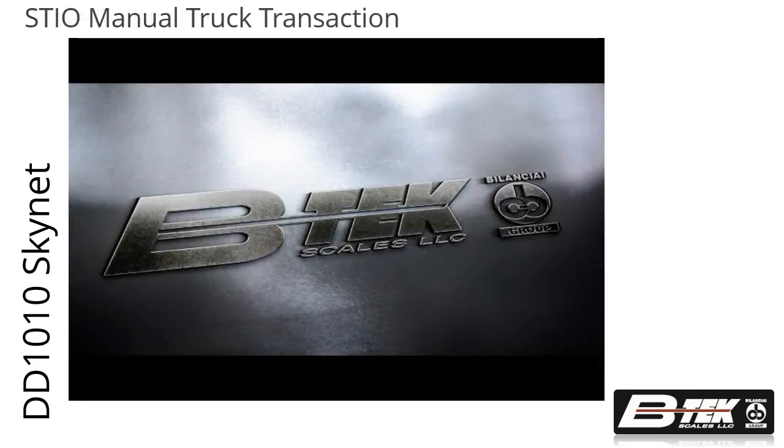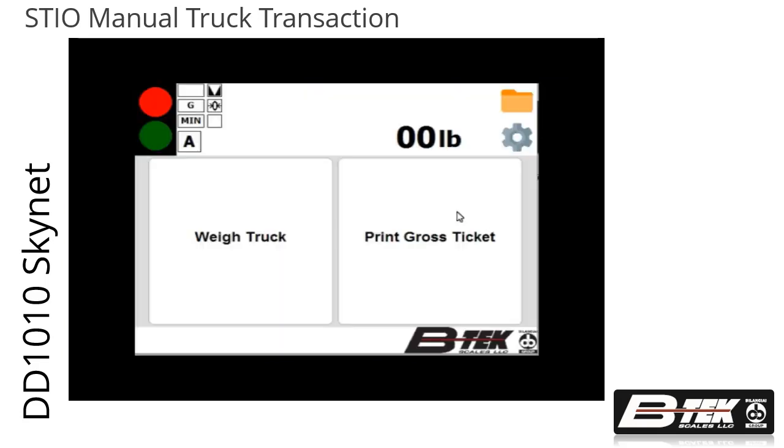Welcome to B-TEK Scales. In this video, I will demonstrate a truck in and out transaction using a manual ID entry. First, have your truck pull onto the scale. This can be your lightweight or your heavyweight. When the scale is stable, press the Weigh Truck button.